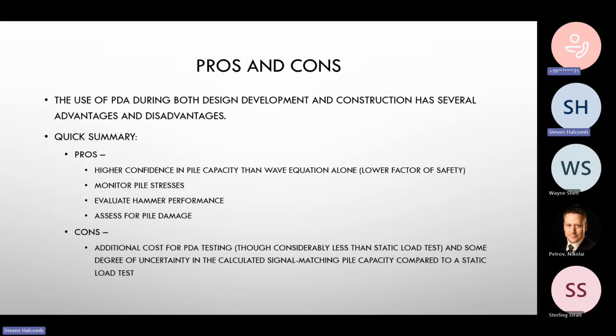As for pile damage, I'm not exactly sure how they do this. I think you should be able to measure the time it takes for the stress wave to come down the pile and bounce back up. If you think you've got a 40-foot stick of pile in there, but the signal is coming back way quicker, the pile is shorter. So the pile is scrunched down, and you're getting signal back like it's only a 30-foot pile. Well, you think you're advancing this pile, but it's not as deep as you need it, or it's compromised at the tip there.